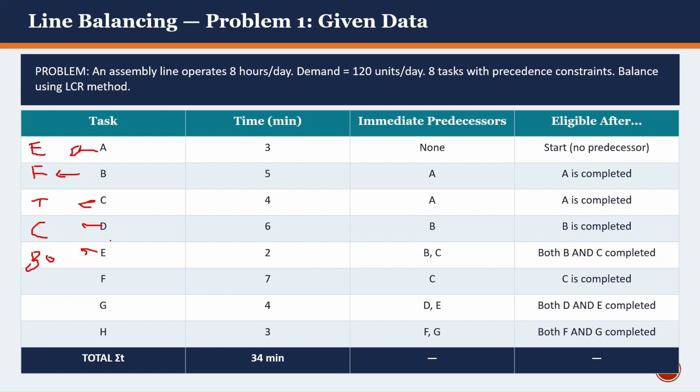So likewise, this is the sequence of operations when we are going through the assembly. The times required are usually found using the work study and method study techniques that we discussed in unit 1. Now, these times are given and we need to balance the assembly. So what assembly balancing do we have to do?